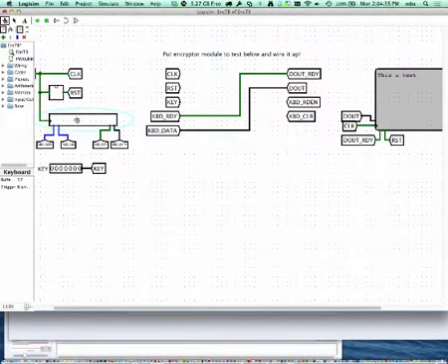If the buffer is empty, nothing comes out. But whenever there's a character, it outputs it for 1 clock cycle. This line, keyboard ready, goes high if there's a character available, and the character appears out here. There is also a line called keyboard read enable, which if you assert low, ignores the clock, so it does some equivalent of clock gating internally.